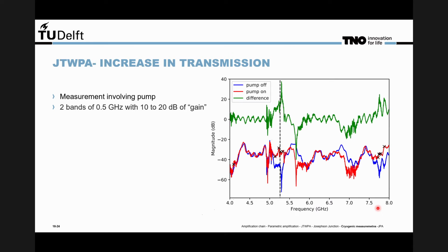The transmission through the TWPA was always lower than the transmission through the cable measurement. So we expect that this great loss is due to the niobium titanium nitride short to ground. There are some ways to prevent or remove this kind of defect, but unfortunately, this didn't fit within the time planning of my thesis.